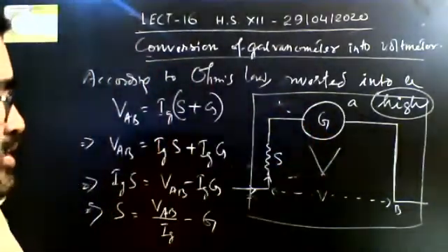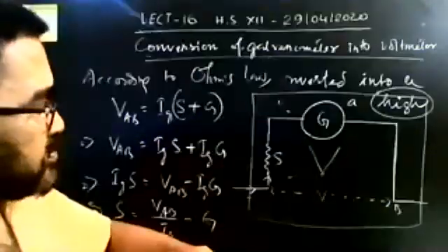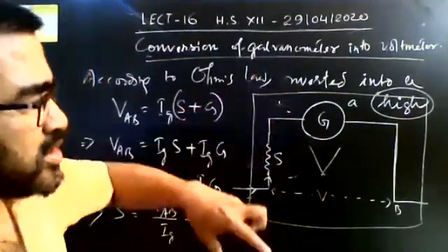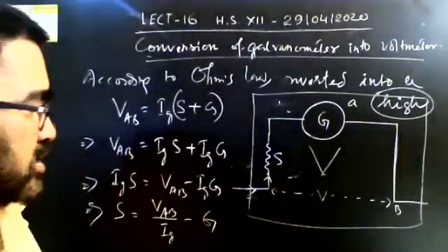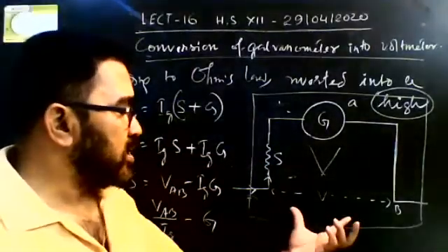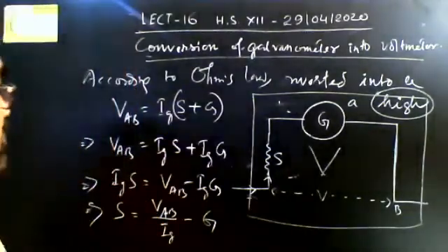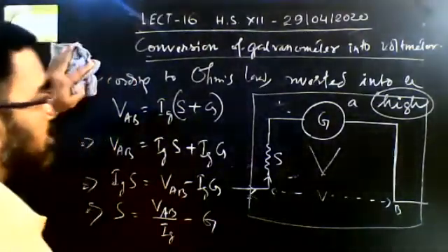As soon as you connect a shunt resistance having high value in series, the galvanometer immediately converts into voltmeter. Then the two points will be connected to measure the potential difference. So let me show you one example of how we can solve a problem.